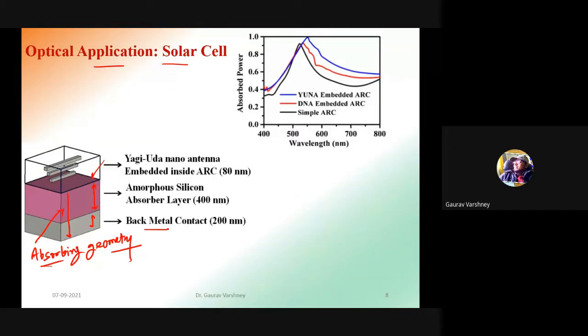And at the top we can provide some resonating structure, like in an absorber. So you can see this is the concept of an absorber in the solar cell: at the back side the back reflecting plane, then the spacer, and then the resonating unit. In the simple case, the main absorbing unit and back reflecting plane are still called a solar cell, because silicon also has the property of absorbing the incident optical electromagnetic spectrum.